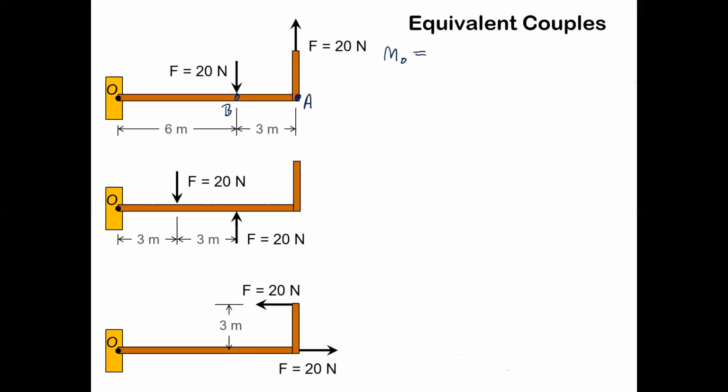But now that we have that second force, it's going to be the same no matter where you check it. So the moment about O is going to be the sum of M1 about O plus the moment of F2 about O, and that's going to equal, well, if we call this F1, it's going to be 20 times 6. That's going to be minus 120 Newton meters, right? Because this one's going clockwise. You see that? This guy's causing a clockwise sense.